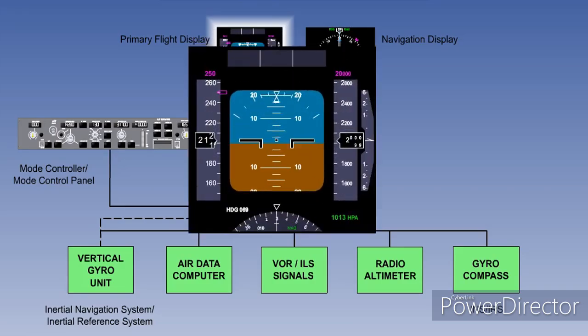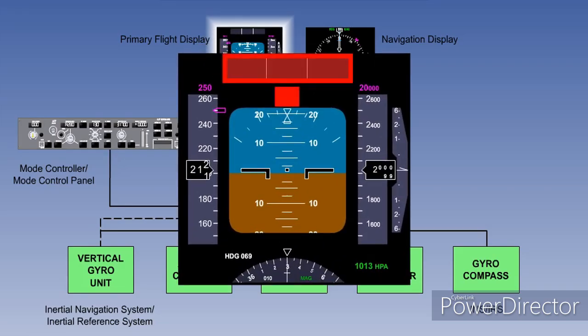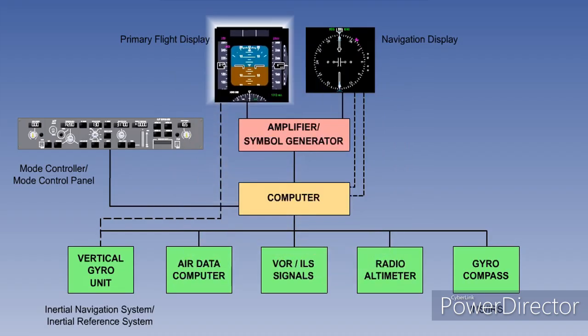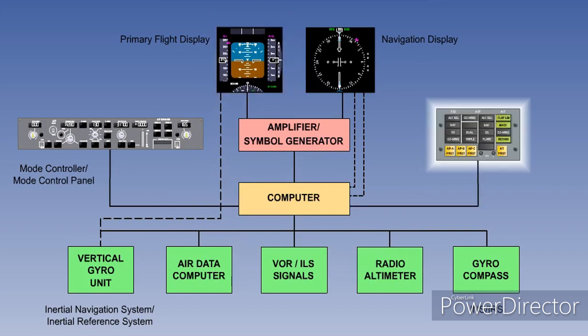To be able to operate the system successfully, crews need to know which mode the flight director is operating in, and so we have flight mode annunciators, normally displayed on the top of the primary flight display, or separate mode annunciators on the pilot's panels for analog displays.